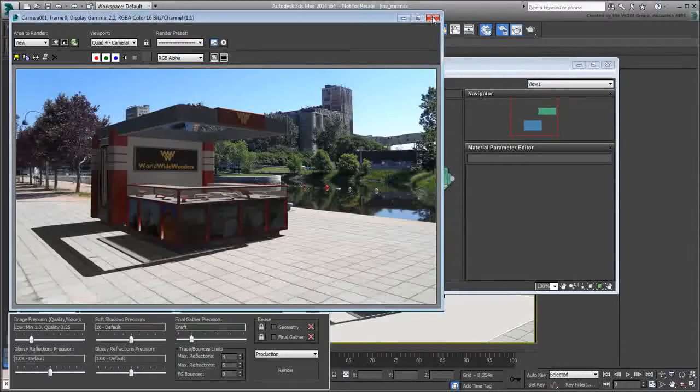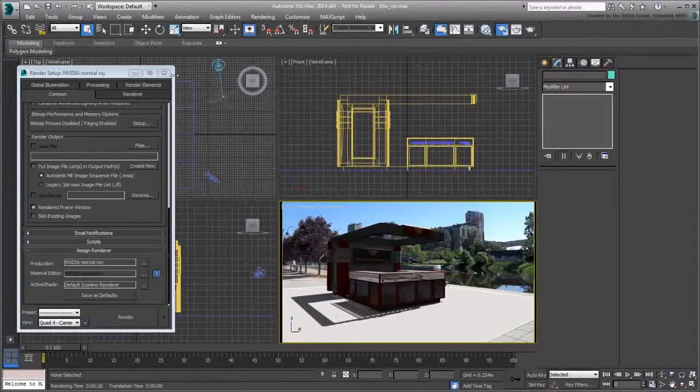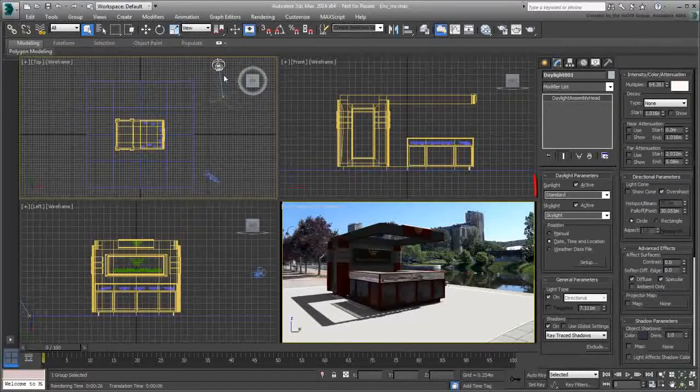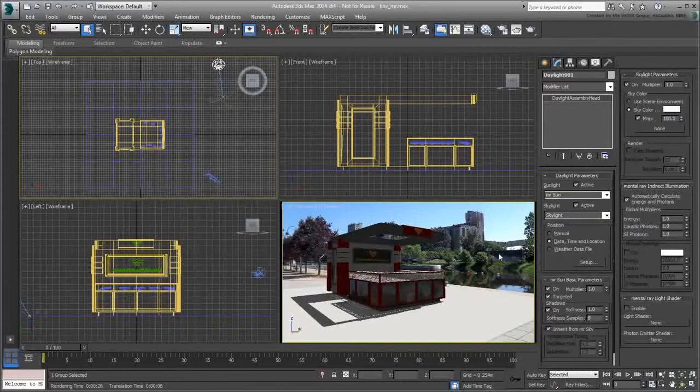Close the material editor and the Render Setup dialog. Select the daylight system and go to the Modify panel. The sunlight is currently provided by a standard light. As mentioned before, this is just a standard direct light and is not physically accurate. Instead, choose the MR Sun option, which is a photometric light and acts closer to how sunlight should behave. This means, among other things, that you wouldn't need to worry about position and beam sizes anymore. The skylight option is still used from earlier. This will do for now. We'll come back to it in a minute.